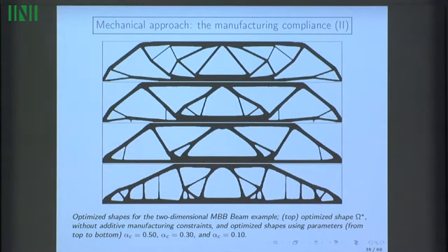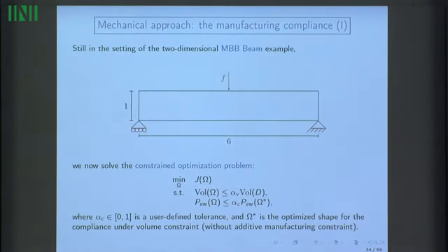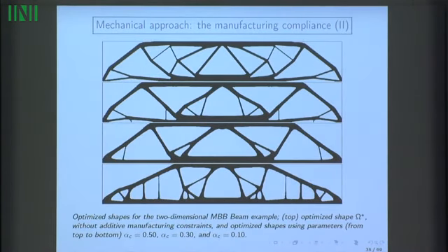So this is the optimized design without any overhang constraints, and these are the optimized designs by strengthening the weight, the threshold for the overhang constraints. So these are the optimized designs with a stricter and stricter threshold for this overhang constraint. And so there is a remark, it's okay, but it's not very good. So obviously these large overhangs which are in the lower part of the shape have completely disappeared. But so you have much fewer overhangs in this structure here, but still the large overhangs which are on the upper part of the shape have not disappeared.